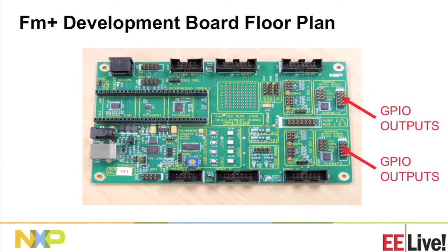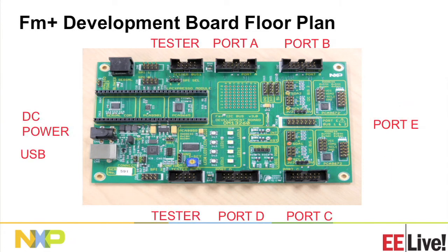And finally, as I mentioned earlier, on the right-hand side, GPIO outputs. They have 10 pins, 8 channels, power and a ground, so you can connect all the hardware there. In the kit, we have a strip PC board that has 8 switches and 8 LEDs on it. So you can then plug those together with the supplied ribbon cables.